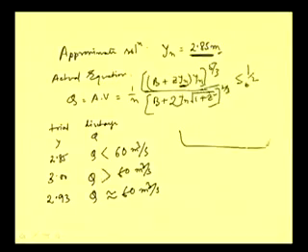So the highest width observed is 20 kilometer around. So that way it is though braided, in the flood time sometimes it flows covering everything. And in this sort of situation, the difference of depth, even a centimeter, matters a lot, because with that difference of depth, our flow discharge changes grossly, because the size of the channel is so large that if our depth changes by a small amount, the flow discharge changes a lot.